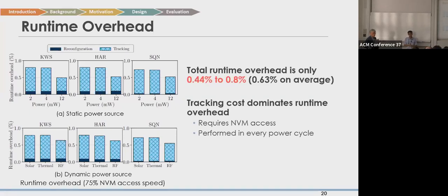And the second question, which is related to that: in case of a multi-core system, what is your protocol for writing back the inference progress that you made from volatile memory to non-volatile memory? Protocol for writing back the result. Here we use the stateful inference approach, and there is another story. For stateful, the amount of data to preserve the inference progress is minimum, and we only write one value for each neural network output. So we only need very minimum non-volatile memory access.